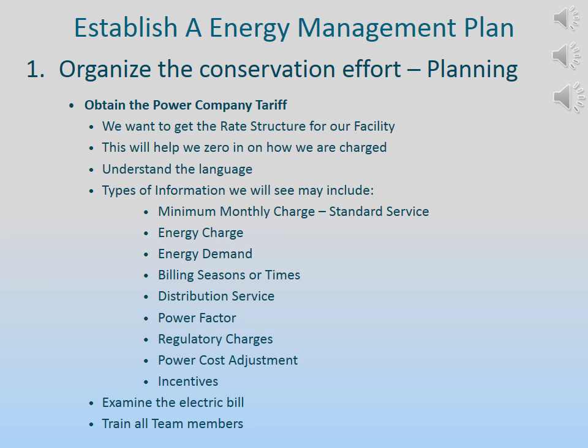We can also see that this tariff has a power factor charge, saying that if we are less than 90% or 0.9, they can charge us. We really need to study our own tariff, but this is the exercise we should go through and do while reading our tariffs.